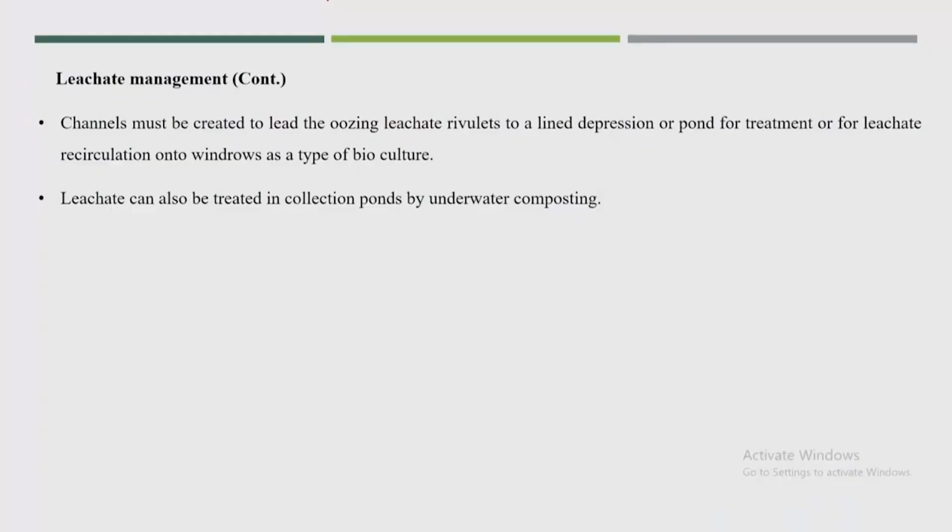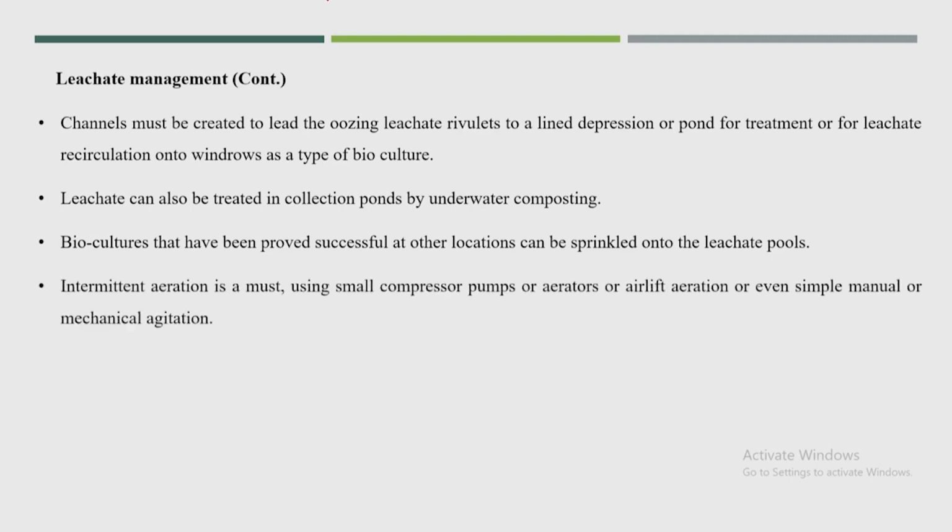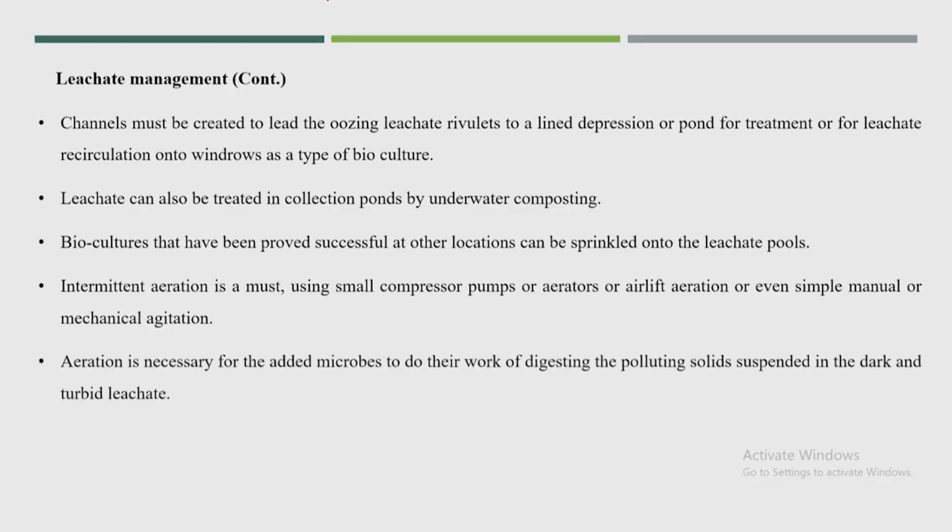Or the leachate can also be treated in a collection pond by underwater composting, but I think this will be a somewhat costly process. Bioculture that has been proven successful at other locations can be sprinkled onto the leachate pool. Intermittent aeration will also be beneficial, and aeration is necessary for the aided microbes to do their work of digesting the organic matter.